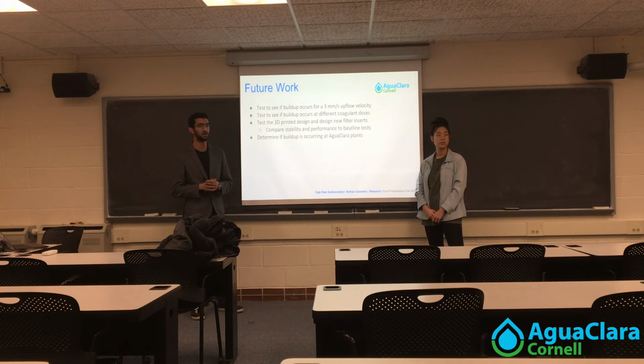The next would also be to test the 3D printed designs that we made at the start of the semester. Although flock buildup was giving us a very stable flock blanket, we do want to avoid it. We want to see if these 3D printed designs were able to produce an equally stable and an equally efficient flock blanket without having the solid-like dense layer which has to be removed manually.